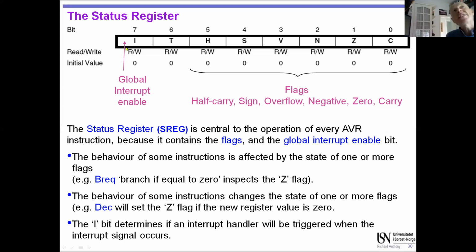This single bit in the status register is one of the most important bits in the whole microcontroller, right? If this is set to a 1, this is the interrupt bit. It turns on the interrupts in the whole device and turns them off. And you can also read this to see if they're turned on and off. Okay, I'll skip that for now.